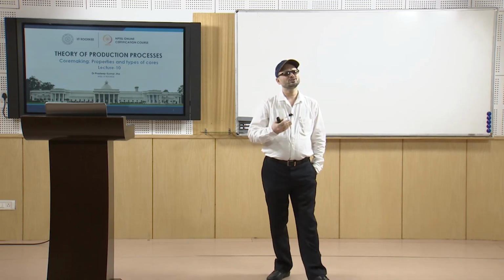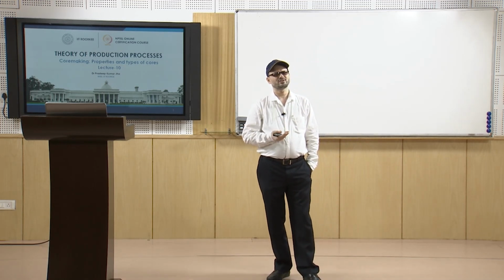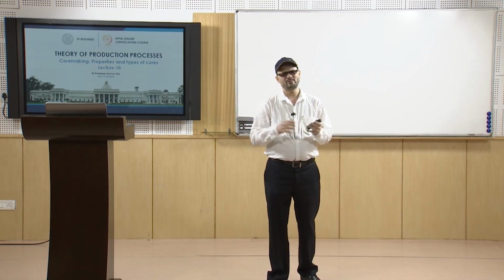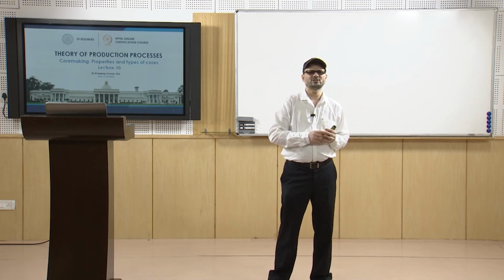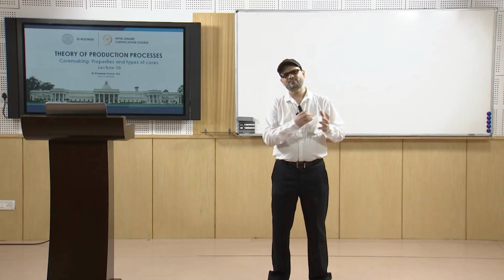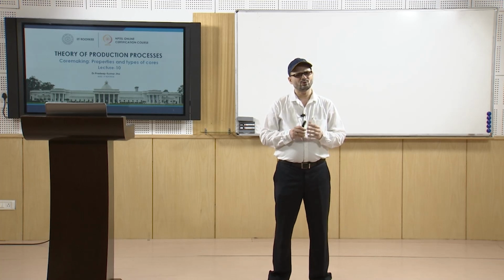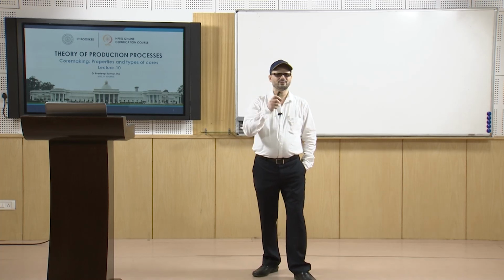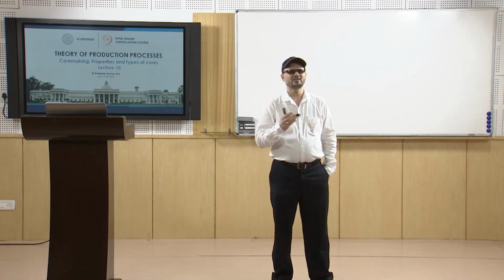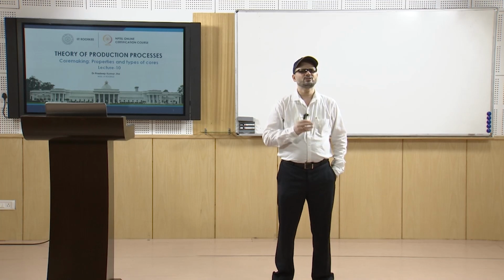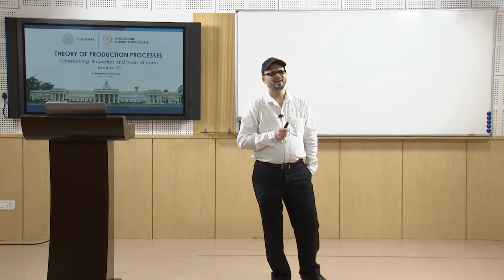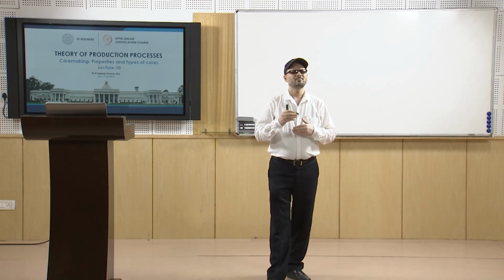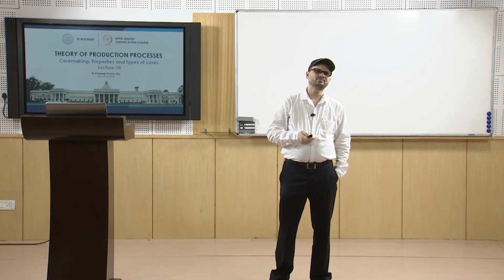It is even used in the case of permanent molds. In a permanent mold, as we know, you have two dies. The die will be closed, then the solidification process will finish, and then every time you have to take the core out. So, core can be used even in permanent molds. As we discussed, it is normally surrounded on all sides by the melt, so it is subjected to much more severe thermal and mechanical conditions, and stresses also act upon it. So, it should have better strength than the normal molding sand.